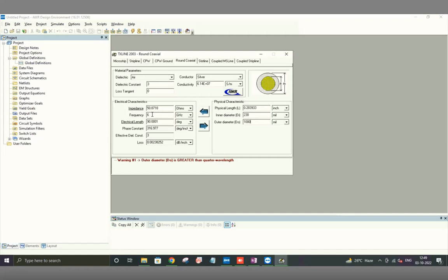At this frequency. So if I make this also 10 times smaller, it will stop suffering. Right? So in that sense, you can scale. If you want to make everything bigger, you make your wavelengths also bigger, then it's fine. It will behave like a nice coaxial line. But if you're working at 6 gigahertz, you cannot make a transmission line with these kinds of dimensions. It won't work properly. It will still propagate, it just won't have a well-defined characteristic, and you'll start exciting other modes. Okay. All right.